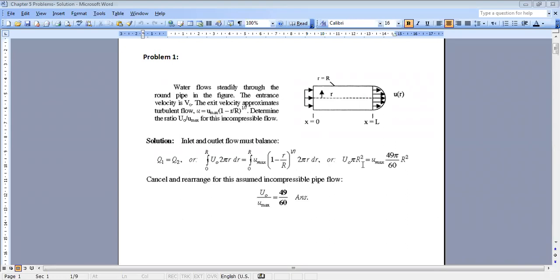If you want to multiply by pi r square, which velocity will you choose? You have a velocity that is varying from the center towards the end. This is why you should do integration. Your integration is from the center to big R, of u as a function of r times 2 pi r dr. So now all you have to do is perform a simple calculation. You integrate for the boundaries given.